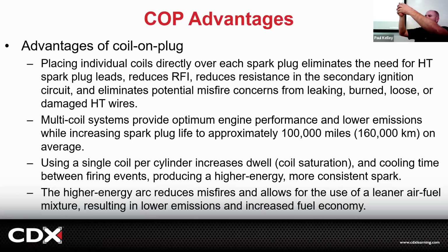If the coil on plug only has secondary down in the tube, it's more safe, right? So this is just better in 1,000 ways. And a lot of times they can go 100,000 miles plus on average. And we are also doing longer life spark plugs, which we do cover, right? And because they only fire once per cylinder, we can increase the dwell time because they're not firing for every cylinder. They're only firing for their cylinder so they can reach their full potential. There's just a lot of benefits.